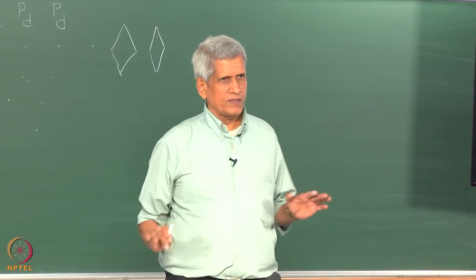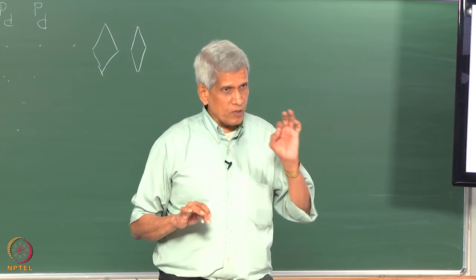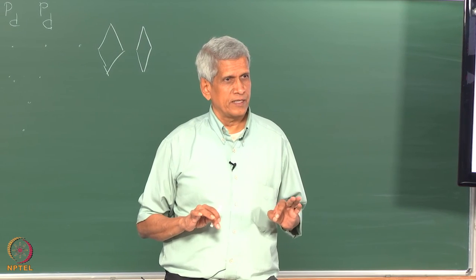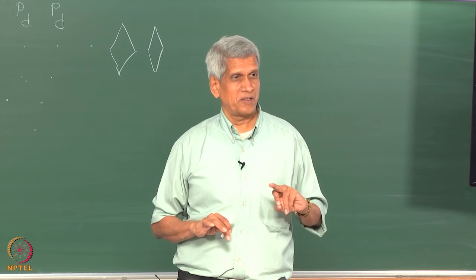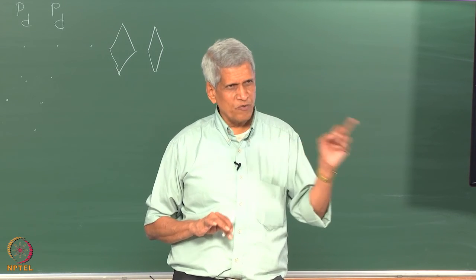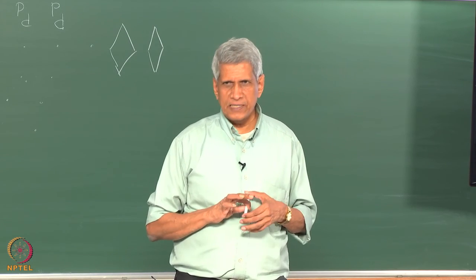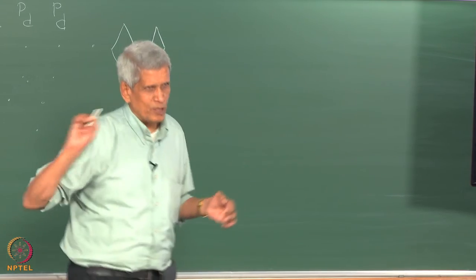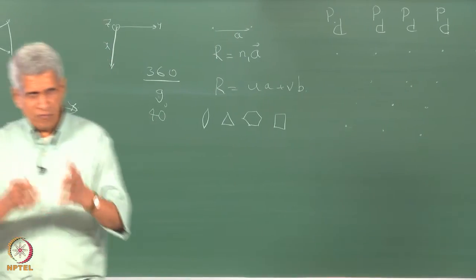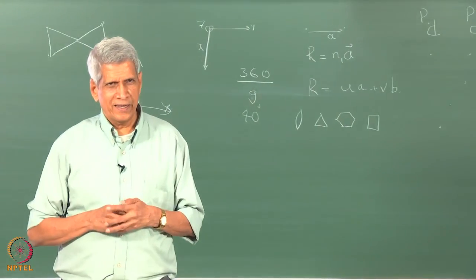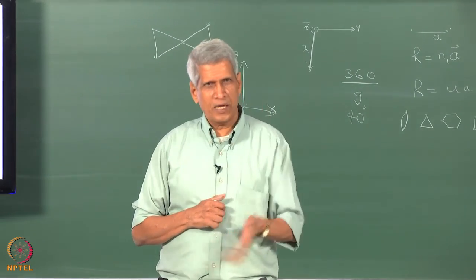Okay. Earlier it was thought that the periodic arrangement is with respect to translational periodicity, because quasi-crystals do not have a translational periodicity, but they have a symmetry. 5-fold symmetry is possible, but periodicity is not possible. You understand that? That is the basic difference between these 2 structures. But generally when we talk of periodicity, we talk with respect to 1 dimension, 2 dimension and 3 dimension, correct? The one which appears as 2 dimension which is periodic, if I look at it, we talked about a reflection, right, with respect to a plane mirror.